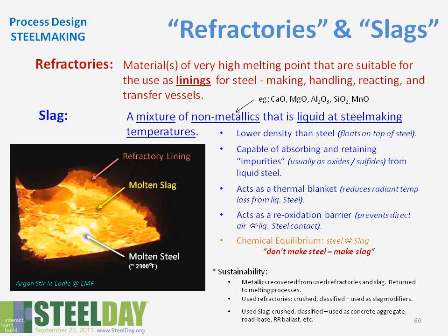Okay, so I mentioned two other terms, and I promised not to be too jargony. What's the difference between a refractory and a slag? Essentially, a refractory is a material of very high melting point that's suitable for use in lining of a vessel. Here's a picture of one of our ladles here at Steel Dynamics. The refractory back here is basically a brick. It's a lining. It goes inside a steel vessel.